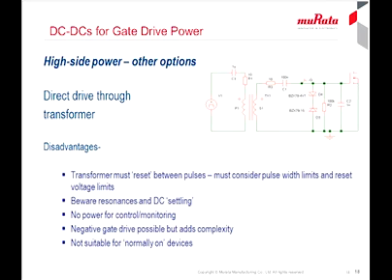If the transformer is AC coupled, as in the diagram with C3, it will naturally reset, but now the capacitor will resonate with the transformer inductance, producing low-frequency modulation of the PWM signal until the resonance settles. This will happen on start-up and every time the duty cycle is changed, risking inaccurate gate drive voltages while it happens. Again, when there is no PWM signal, there is no gate drive voltage, so no power for fault detection and monitoring.